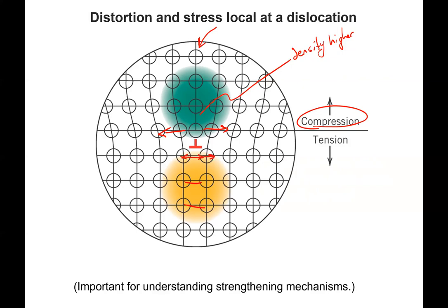But these are stretched outward a little bit to try and accommodate and alleviate some of this compression. So what that does is then create a tension on the bottom part. So the bonds in here should be slightly bigger than they would be in the bulk. Okay. So compression on the side with too many atoms, and the result of that is a tension on the bottom.